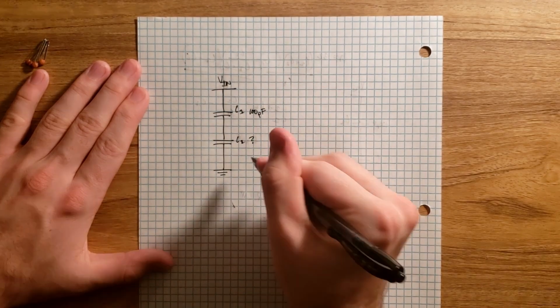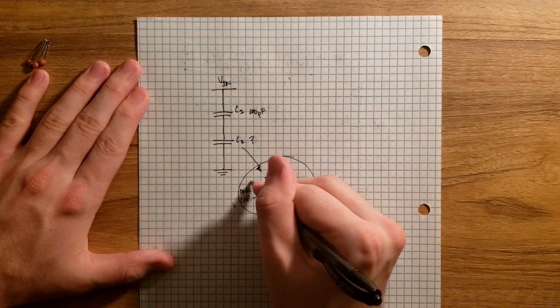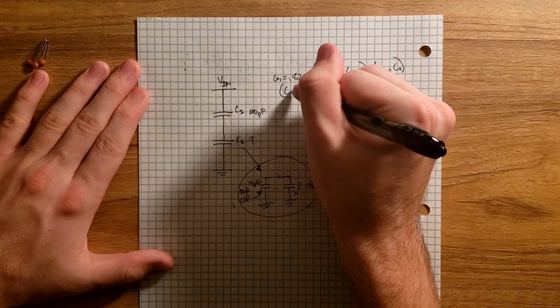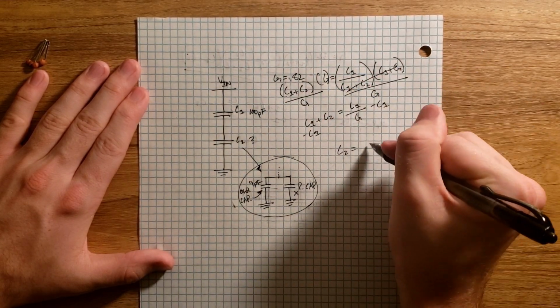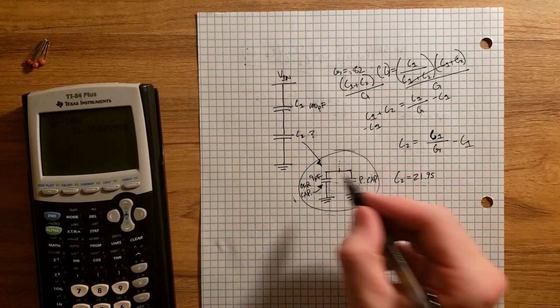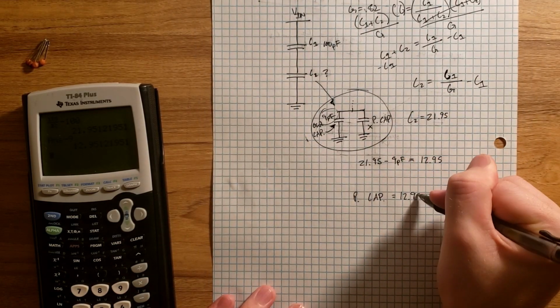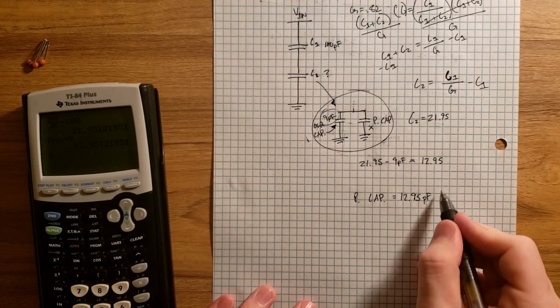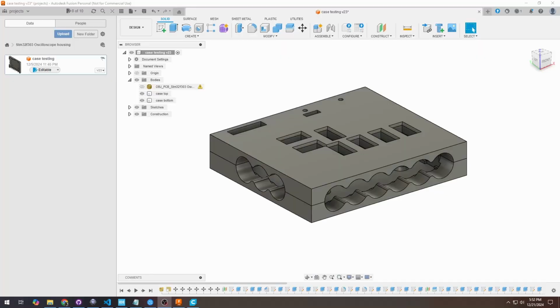At this point, we can actually calculate the parasitic capacitance. This value is actually only as accurate as the capacitors that we used, and there's all sorts of errors in this calculation. I want to post a more accurate value on my GitHub later, but this is what we're going to use for testing purposes, and then we can tune more specifically from there.